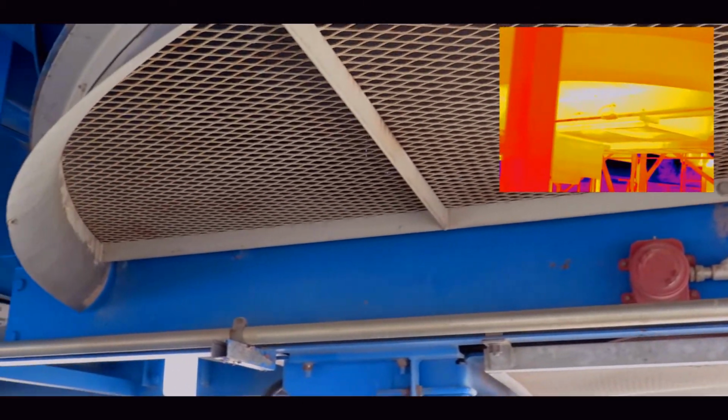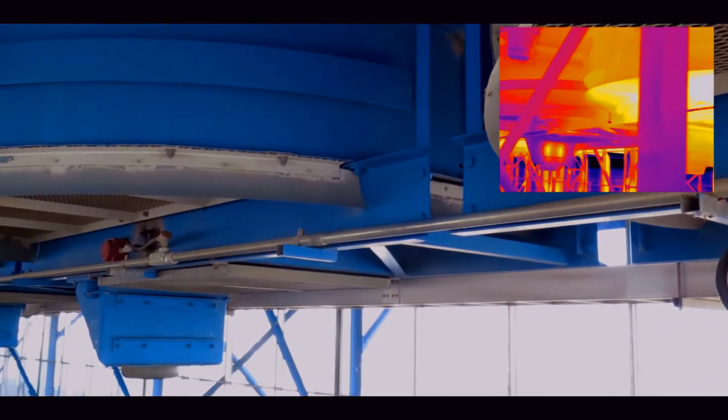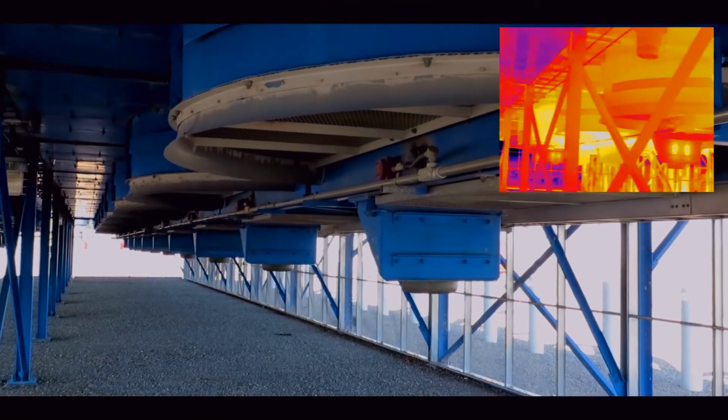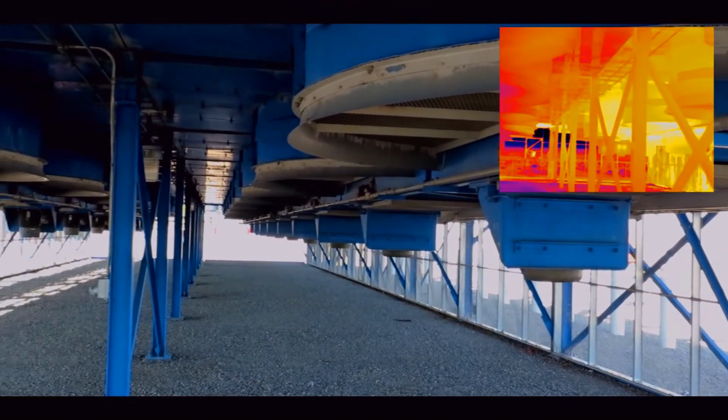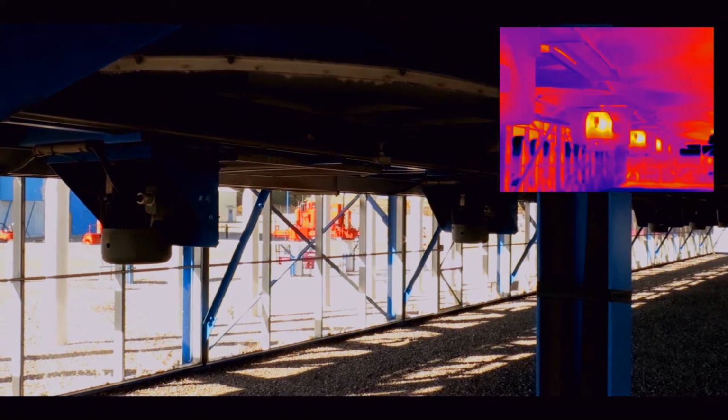There you can see one of the fans. In the upper right-hand corner, we have the infrared camera showing this is a case where we're cooling a gas. And so air is being forced up each of these different units. There's a big fan connected to an AC motor, and there you can see the AC motors. The airflow goes up through and across the tube bundle, which is then cooling a gas. And so that is a gas-to-gas heat exchanger, and sometimes also referred to as being an aerial cooling unit.